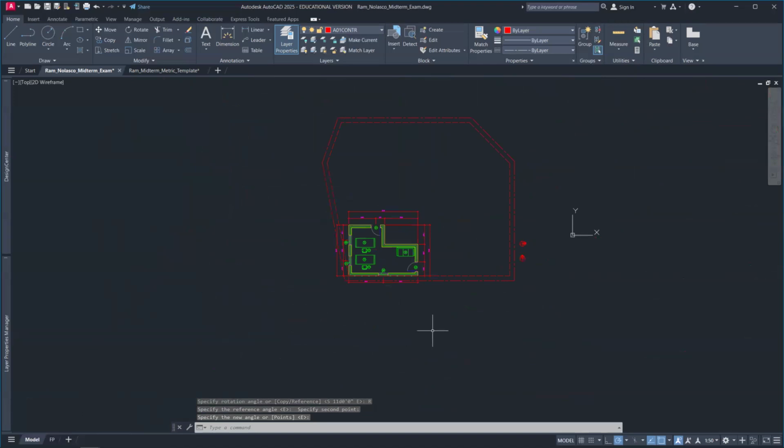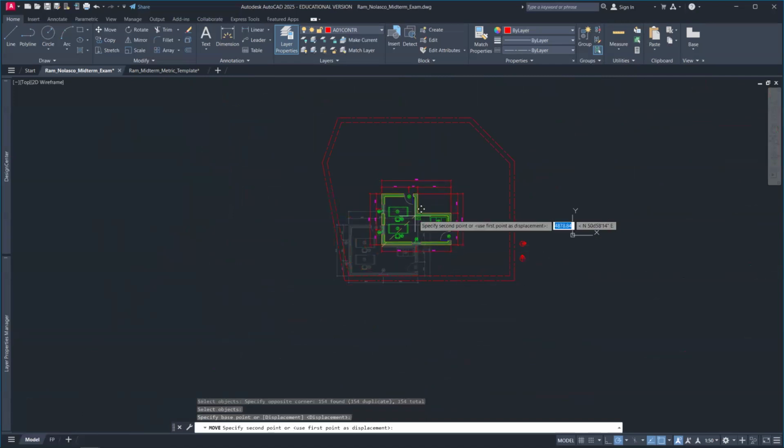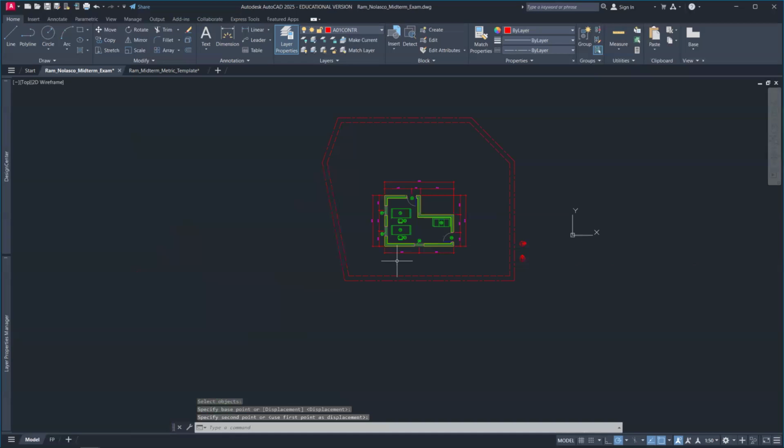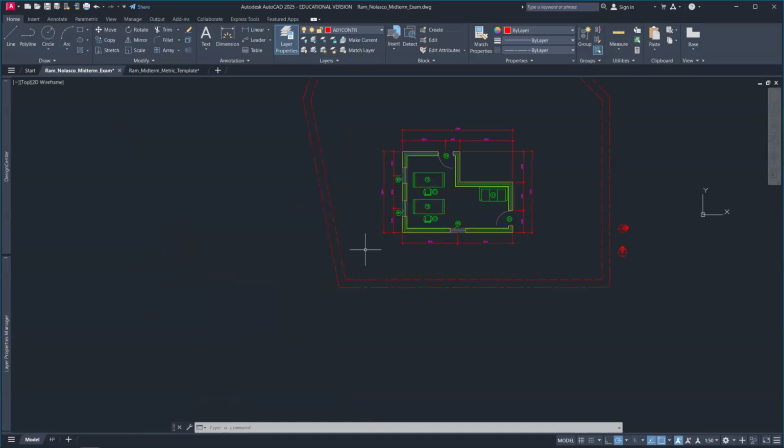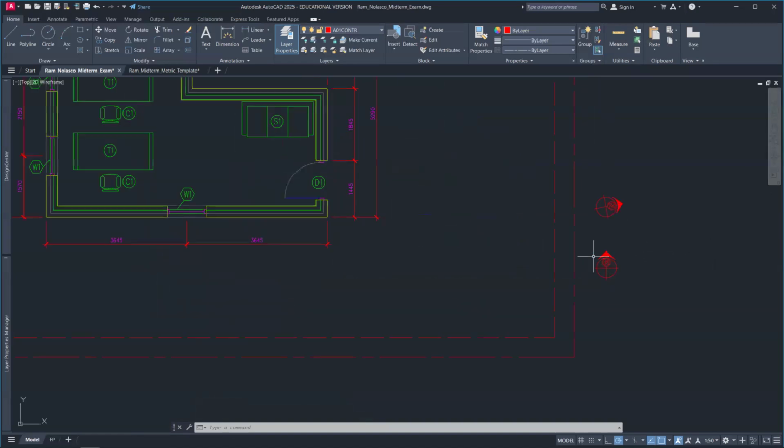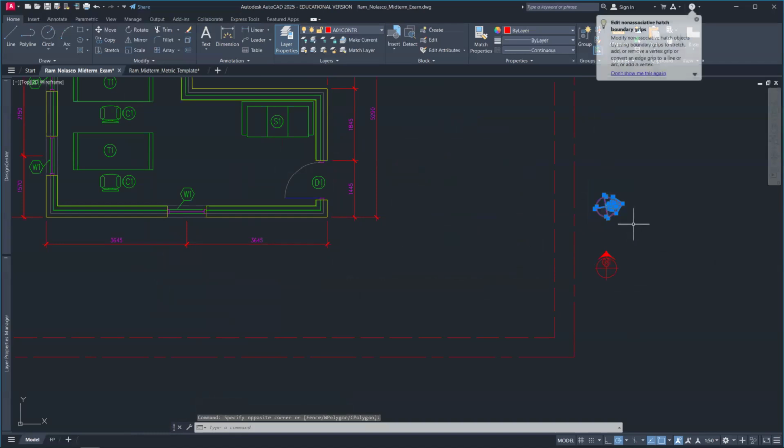And then I can move, P, again, previous. So P is a lot faster, okay? And I can just move it somewhere here. If I need it to be exactly somewhere else, then I need to create that point by way of creating an offset and then intersection, and then from endpoint to that intersection. Now, this project north now is wrong, but it turns out the project north and true north are the same. So you can just say true north, project north, and you won't need this.